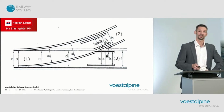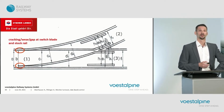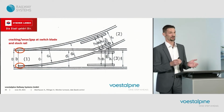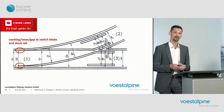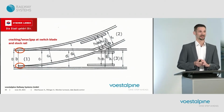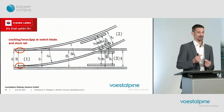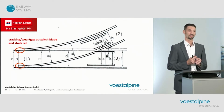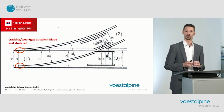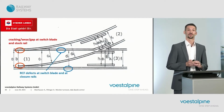which we find in the major track. This is first of all cracking or wear at the switch plate as well as at the stock rail, and very important for the risk against derailment is a gap between the switch plate and the stock rail, which has to be monitored carefully in order to guarantee the safety.